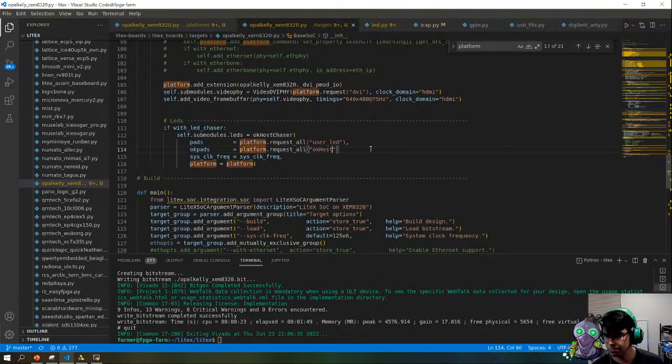So Titan Boy. This is a brand new Python description of HDL. This will design HDL. This is going to connect our Verilog files to a RISC-V SoC. That is our goal here. So this is an open source Python-based SoC description that, when compiled using Migen and LiteX, Migen will convert into HDL. We can look at the HDL file. Hopefully this one works. But yeah, let's try.